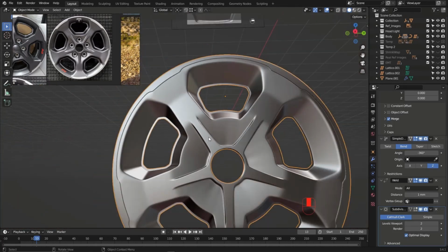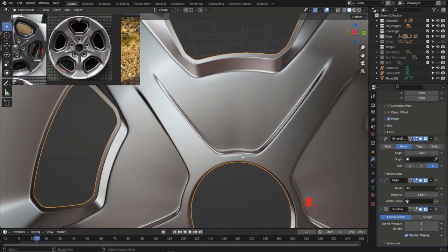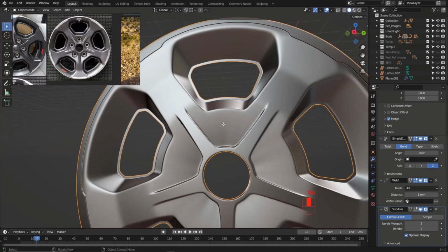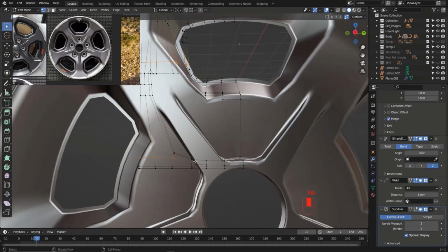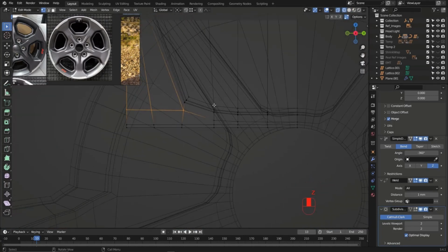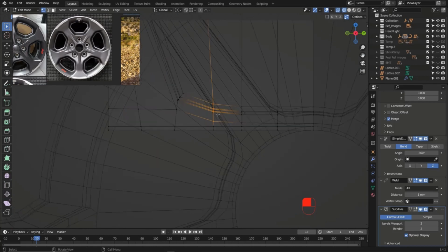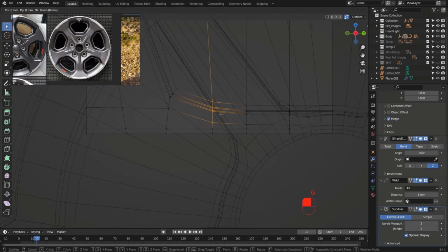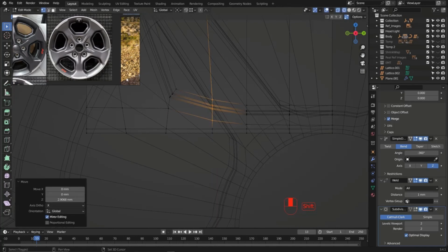That's very cool. Now let's say that we have fixed this area. Now what about this area right here? You can tab again and we can control that in the right view as well. Just go to the wireframe, and let's start with these vertices. Let's move these vertices up a little bit, hit G then Z, and let's see what that will affect.